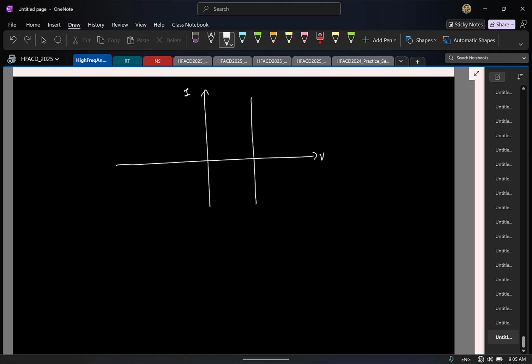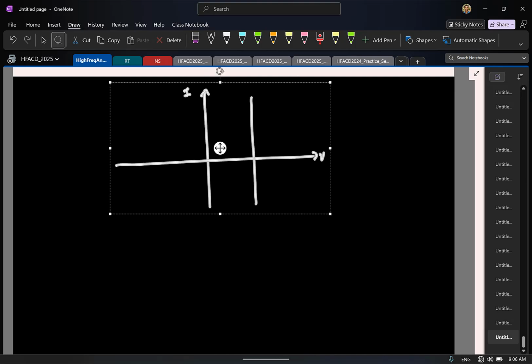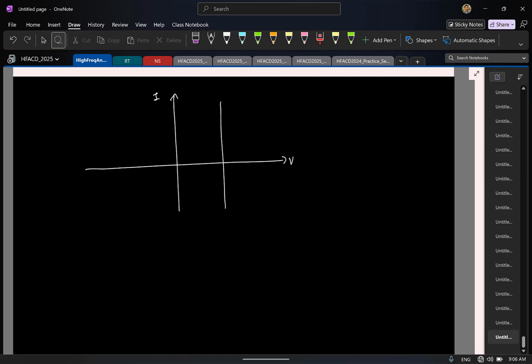Voltage is constant irrespective of the current. Right? But of course, this is the IV characteristic of what element? Yeah, ideal voltage source. If you have an ideal voltage source on chip, you don't have to do anything, but unfortunately it can't do it because a voltage source is an active device, it generates power. On chip we can only have elements that can dissipate power, so we can have only passive devices, right?